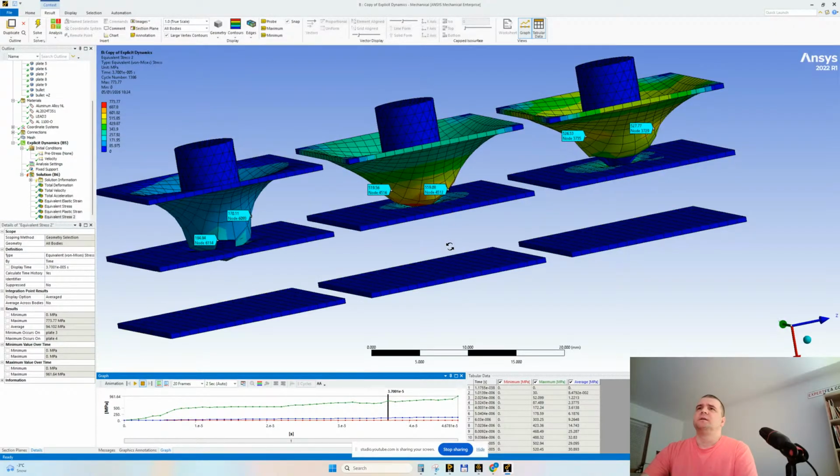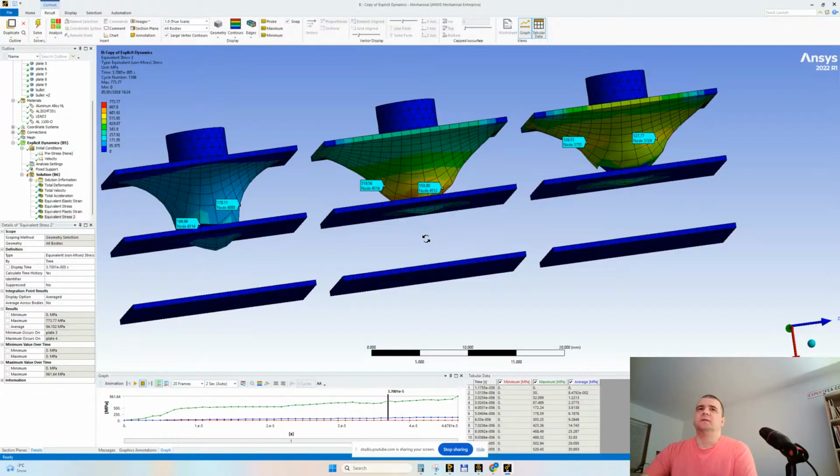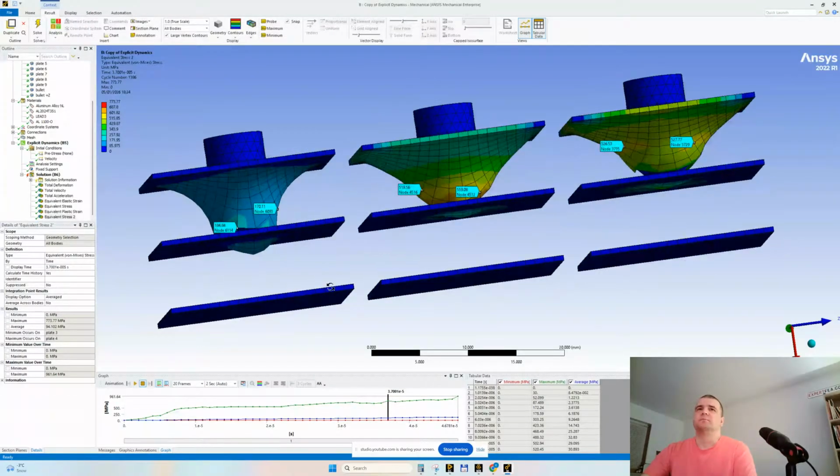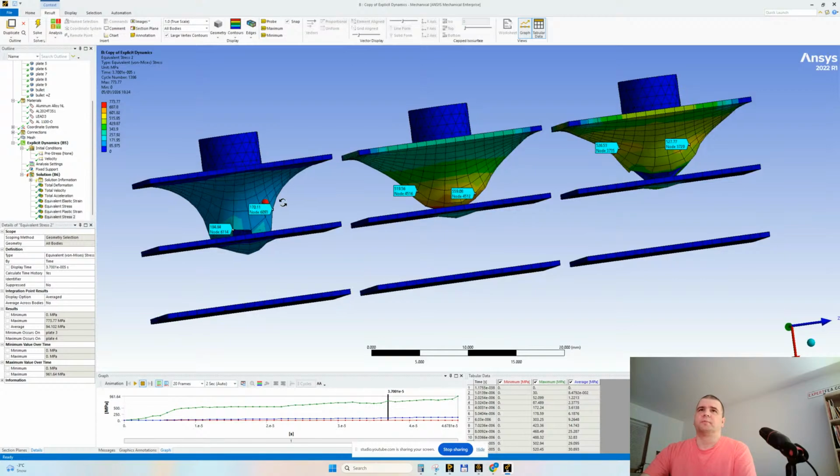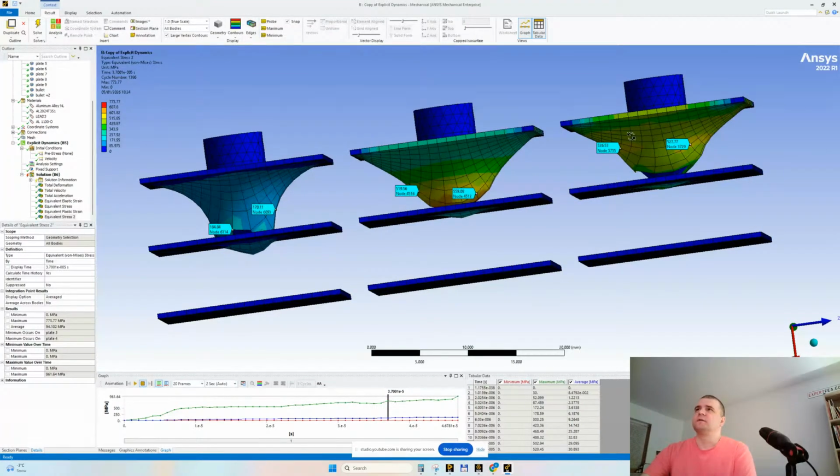Yes, it needs to be debated. Which one is more correct. Okay. My assumption is we cannot have reliable discussions and results with such a coarse mesh because it does not make sense. This to have 100 below 200 megapascals and this to have 500, and it doesn't break here. The elements are elongated too much, all right? Why are they elongated too much?